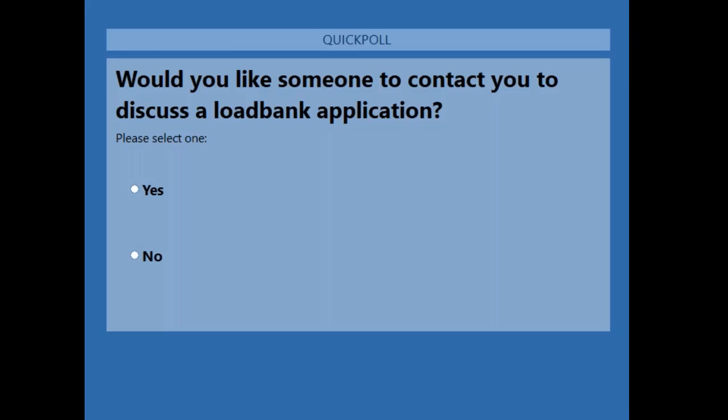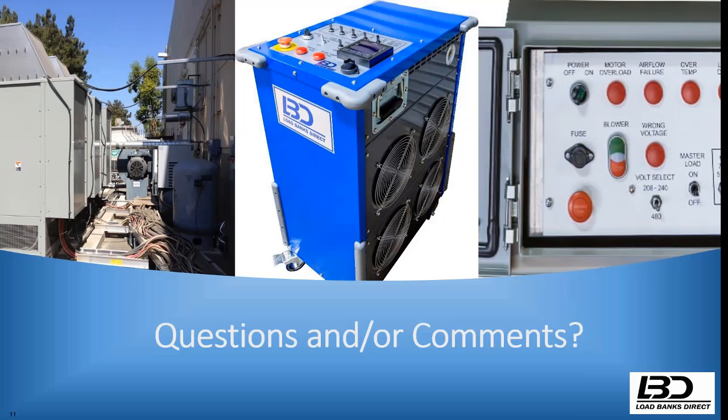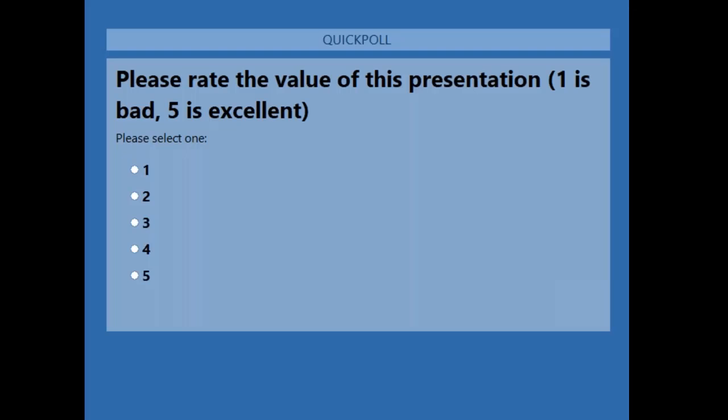Yeah, I would agree with that. Then you'd have a stationary application. It really depends on the application. If the requirement is to do 100% or 110% or 120%, you really need to have a stationary load bank for that application. And a lot of times you can meet the NFPA 110 requirements by just doing a 50% load test for 30 minutes every 30 days.